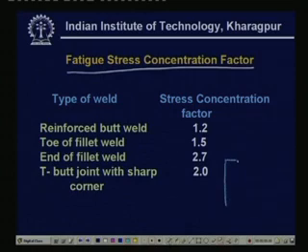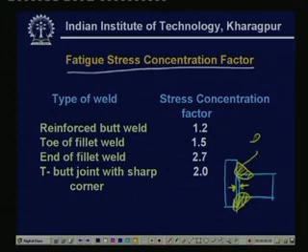suppose we have this fillet here. Now, you see, when we want to make two fillets here, then definitely there will be a gap, that cannot be avoided because of some error. So, this gap E, if you consider the loading, that is, if you consider the real joint, is nothing but a crack. So, therefore, a stress concentration will exist over here. So, there is a large stress concentration here.